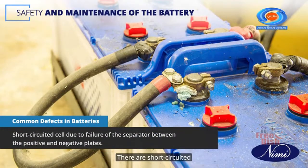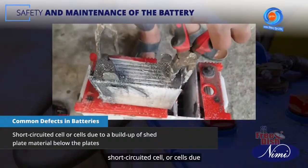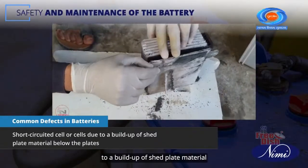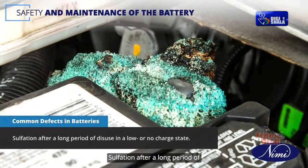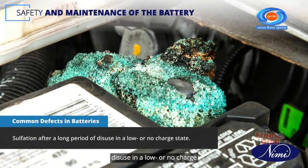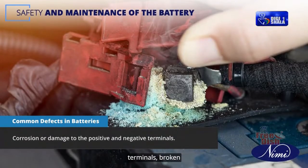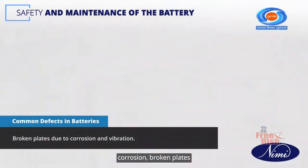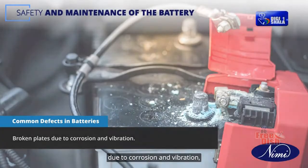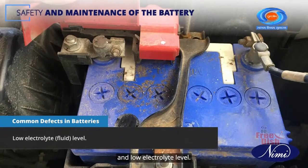There are short-circuited cells due to failure of the separator between the positive and negative plates, short-circuited cell or cells due to a buildup of shed plate material below the plates, sulfation after a long period of disuse in a low or no charge state, corrosion or damage to the positive and negative terminals, broken internal connections because of corrosion, broken plates due to corrosion and vibration, damage to the battery case, and low electrolyte level.